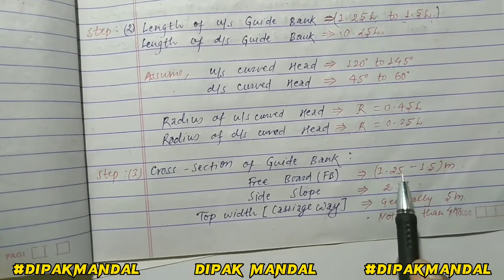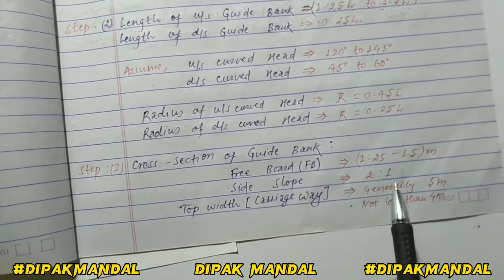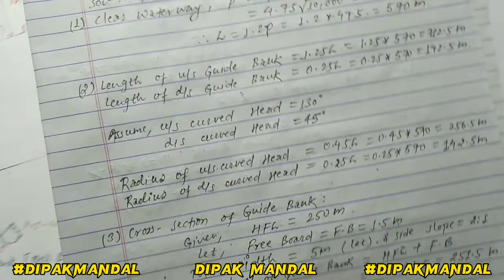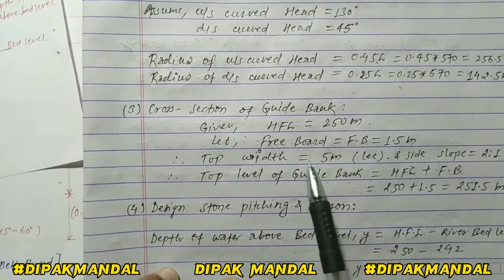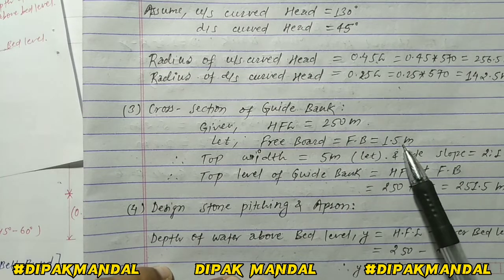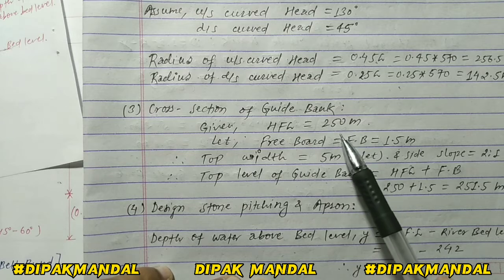You can see here, freeboard we have to provide between 1.25 to 1.5, side slope 2:1, and top width 5 meter. So according to the design criteria we provide these values: freeboard 1.5 meter, top width 5 meter, and HFL is already given in the question.